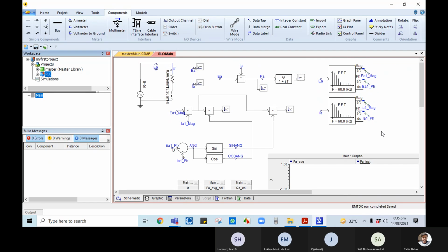Next, if I want to measure the reactive power of my system, I know that Q is equal to VI sine theta, and the real power P is equal to VI cos theta. For that purpose I need the magnitude and phase of my values, which are given as continuous analog signals. So I make use of the Fourier transform, converting to digital and getting the magnitude and phasor. Again, where is this available?